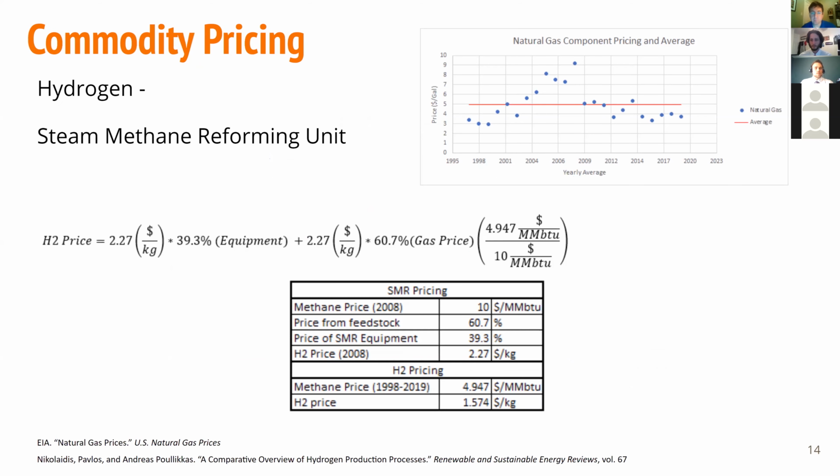Due to the large amount of hydrogen that is required for our system, we will take advantage of the steam methane reforming unit on site. This unit uses methane and high temperature steam over a nickel and platinum catalyst bed to create hydrogen and CO2. CO2 will be scrubbed before leaving the system to decrease the environmental impact.